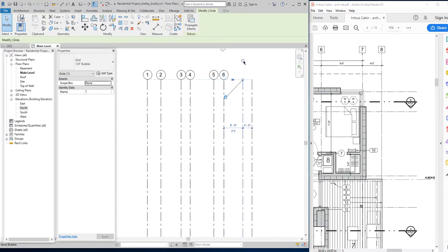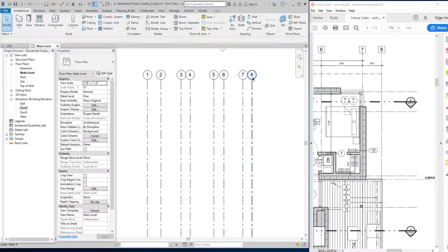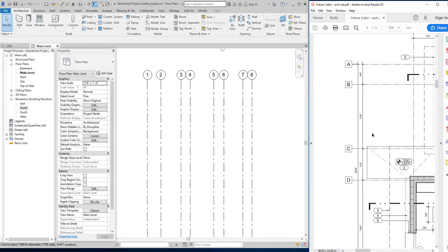It's going to sequentially number these. If I had accidentally deleted number 4 and I want to put number 4 back, it would number it as number 9, grid number 9, and I just have to change the number. Okay. So I also have a horizontal grid here.